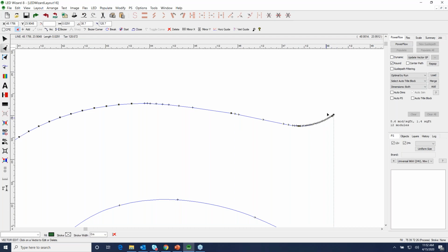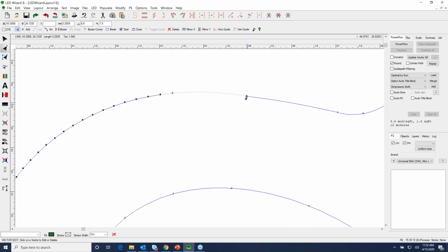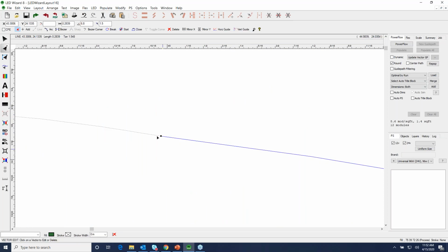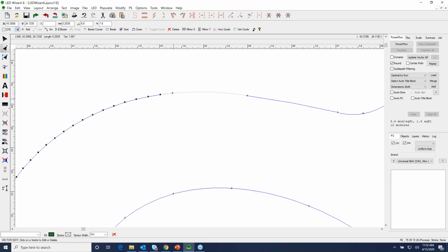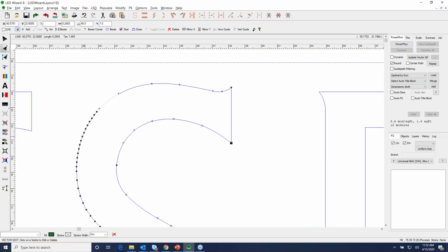All right, so if I start on this endpoint and I go way over here, look what I just did. I changed the shape, and I don't want to change the shape that much. So really, as you do this, let's just go maybe here. You want to visualize arcs, right? You want to say as I go around, what looks like an arc, and here I didn't do a very good job because I have a non-tangent point, okay? Almost tangent. So I can just edit that until it's tangent. So I'm visualizing arcs, and I'm looking to create pretty even spacing.